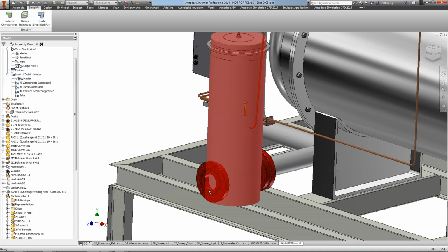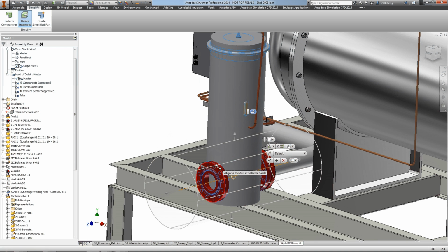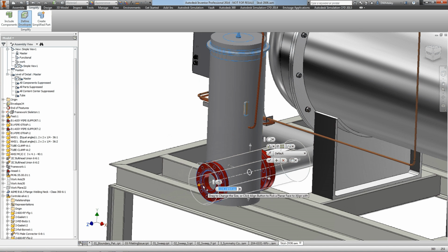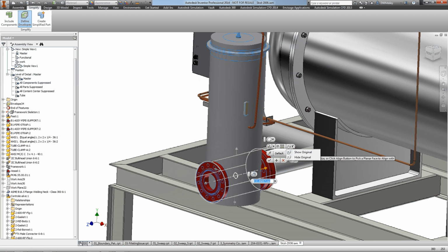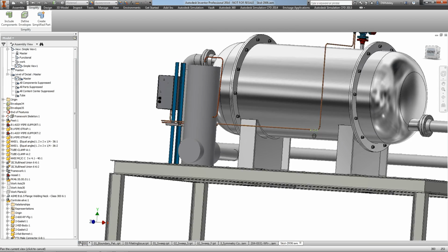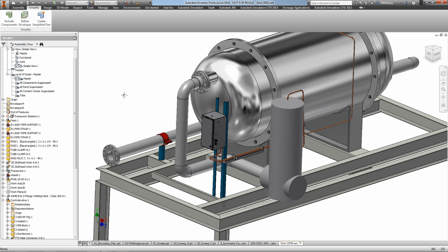But of course I've got a set of flanges across here as well, which is part of it. So again, if I go to define envelopes and select this part, I can now reorientate the cylinder to these flanges, and again I can resize, and I can use a line if I wish. Again, I'll just do this by eye just for speed. And then in this case I don't want to see the original anymore, so I can hide the original, create the solid. The visibility of the original one's been turned off, and then when I create my simplified part, it'll actually create my simplified part of what we see on the assembly and these features here.